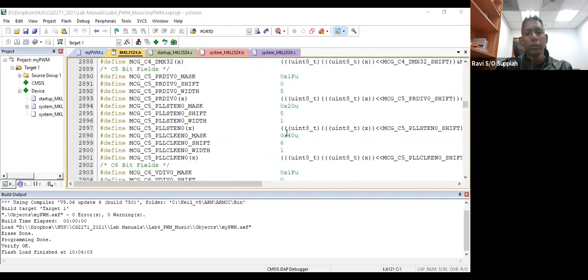With this mask, you know that you are accessing the correct bit location and setting the correct value. If you want to use your own mask or directly write a value, that is also fine. But since we already have these masks, it will be a bit easier to use them.